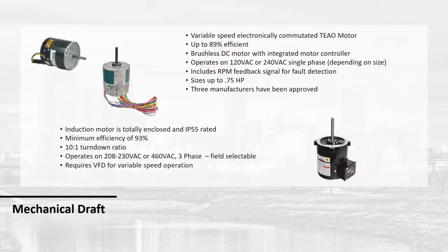We also use high efficiency motors on all of our products. We've recently upped the EC motors up to 1 horse. So it's a direct drive, direct speed signal from the controller right to the motor. There's no external controllers necessary, and that will modulate all the way down to 15% capacity.